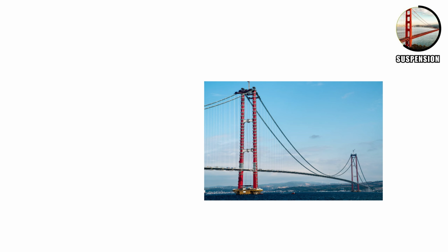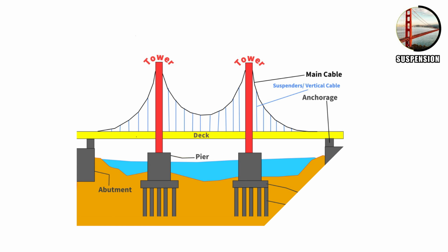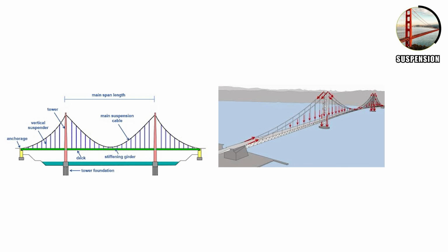Suspended deck bridges are the design most associated with suspension bridges, featuring the longest spans in the world. Massive main cables or chains dangle the road deck below with vertical hangers. Towers on either side prop up the main cables, transferring most of the bridge's weight into the foundation through these towers. The rest transfers into the bridge's abutments through immense anchorages, keeping cables from pulling out of the ground.